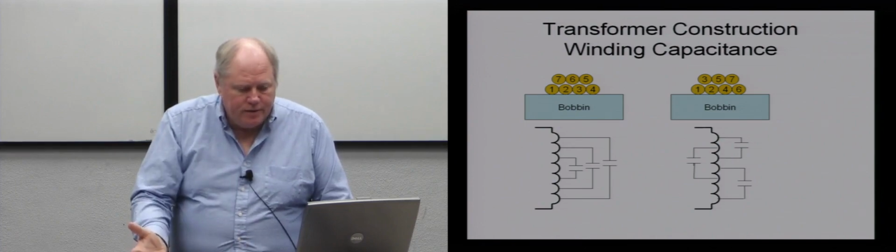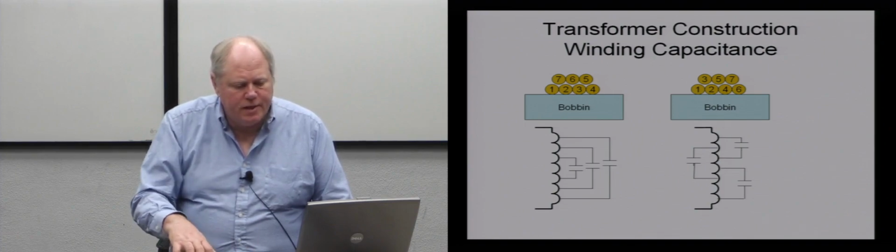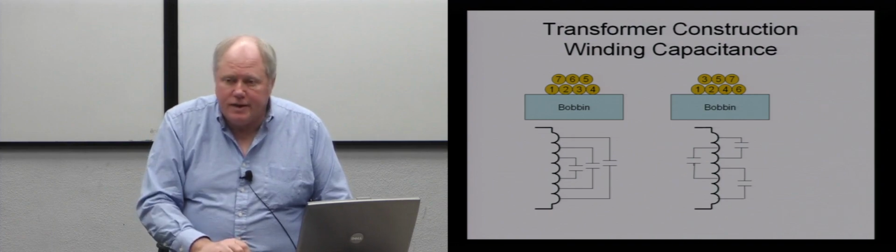And then you've got your effects to the secondary windings to consider. There's capacitances to the core, capacitances to a circuit board underneath, sometimes that's an issue. You just have to make a picture, draw it, analyze it.